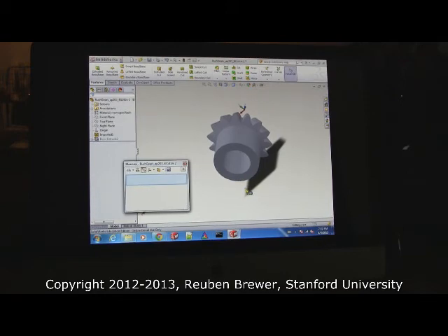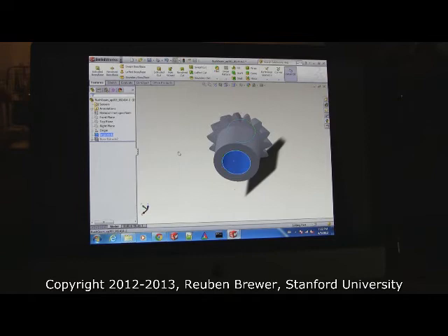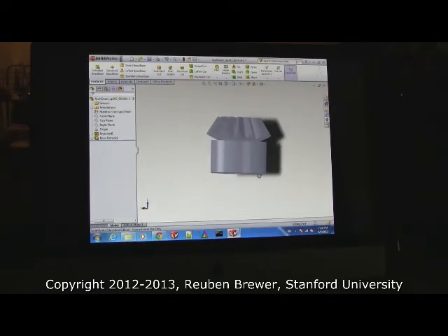But usually you want something special. You want a clamp, or a set screw, or you want it to be this long, or you want a different bore. In this case, this center hole is half an inch, which is 12.7 millimeters. But the shafts we're using in this class are 8 millimeters. So we took somebody else's gear teeth and made it fit our shaft. And we made it fatter because we're 3D printing it, which means it's kind of weak, so we want more material there to be safe. Okay, we're going to move along.